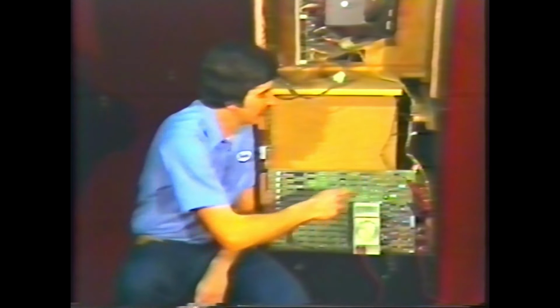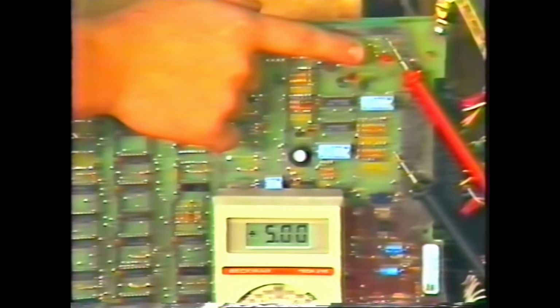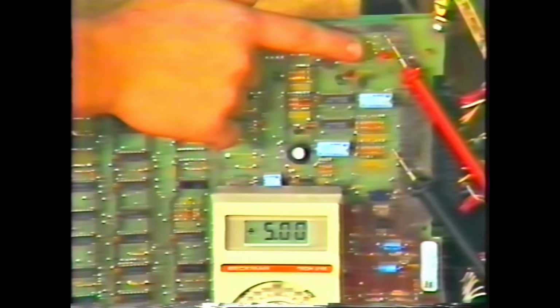To make it easier for you to test the power supplies in a game, many manufacturers are now installing test points right on their printed circuit boards. Well, this makes your job real simple. For instance, here on this Tempest printed circuit board by Atari, there's a test point marked GND for ground, and we'll connect our black meter lead to this test point. There's also a 5-volt test point on the printed circuit board, and it's right here, right next to this red LED that is glowing to indicate that we do have the 5 volts to the printed circuit board. With the meter set to the 20-volt range and the red and black leads in place, we can see the meter reads exactly 5 volts.